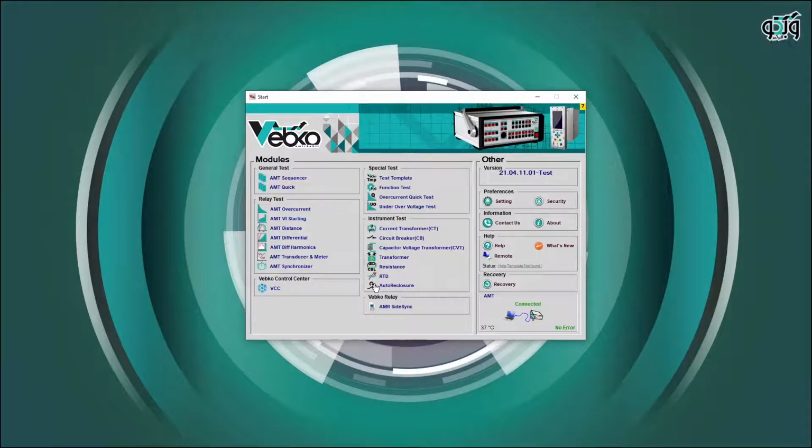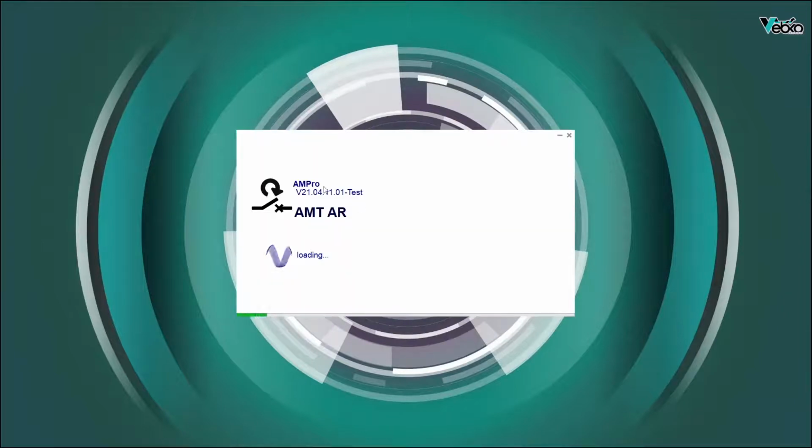The user can begin the test after ensuring that the necessary conditions for the recloser to perform are met. These conditions include activating the protection, not blocking the ARC function, being able to open and close the breaker, and having the closed state of the key. To adjust the relay wiring, the user can use the connection diagram from the manual.